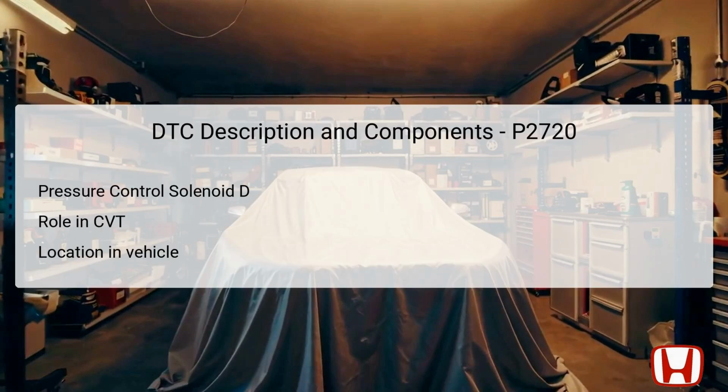effectively. The Pressure Control Solenoid D is an integral part of the Honda CR-V's continuously variable transmission, CVT. Its primary role is to manage hydraulic pressure, which is crucial for the appropriate engagement of clutches involved in the transmission process. The solenoid is engaged by signals from the Powertrain Control Module, PCM, ensuring that the transmission adapts efficiently to driving conditions. In a Honda CR-V, this solenoid is typically located within the transmission assembly, necessitating careful access when